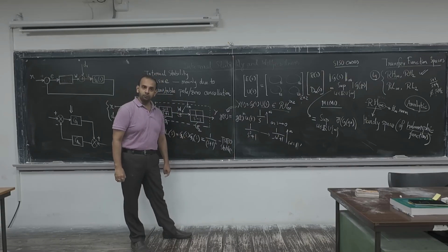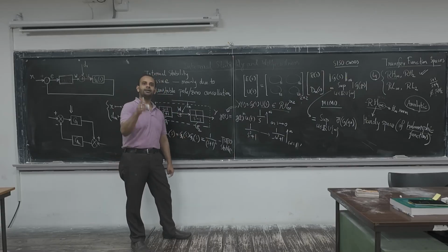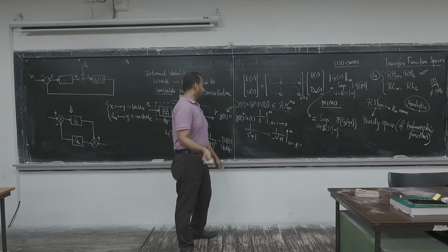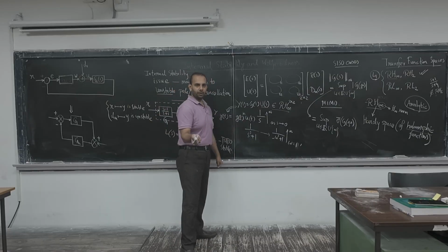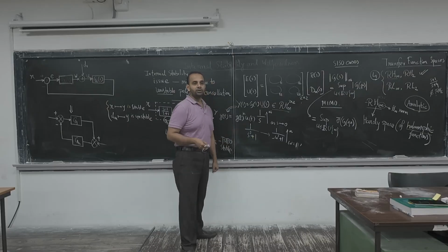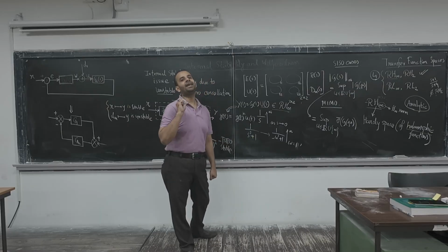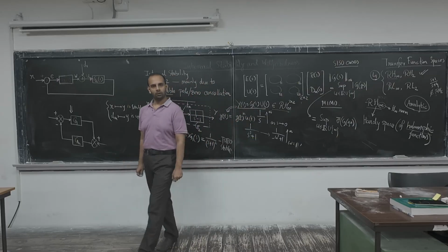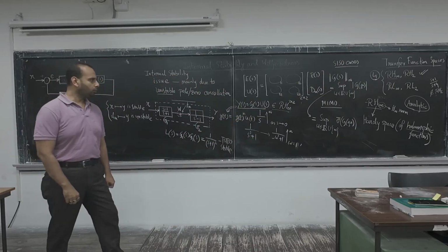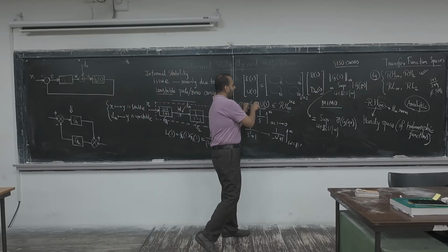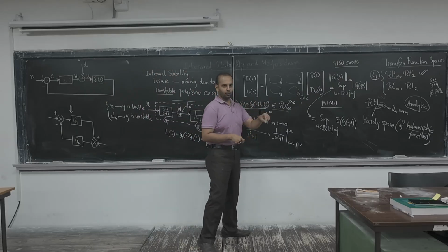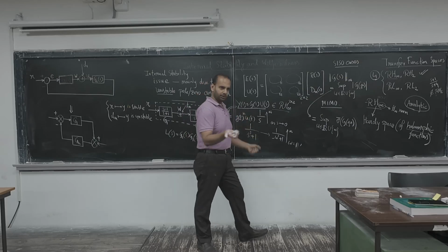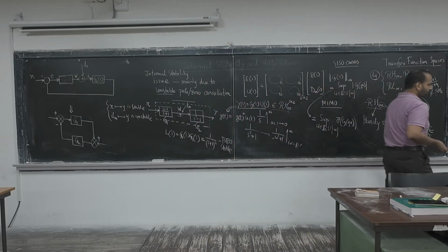And if you have to remove the convolution, then you have to write the integration from 0 to t of e to the power all those things, right? So that is what I was talking about. In the time domain, we don't exactly get the feeling of a gain, but it is pretty straightforward in the frequency domain. That means there is some gain acting on the input signal, and the input signal is being scaled by that gain. That is basically the concept of gain.